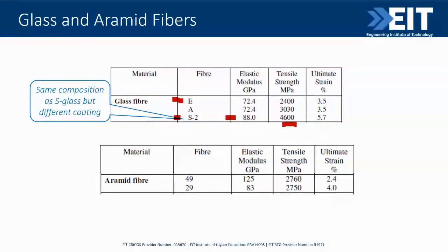That's glass fibers. There's another kind, which is aramid fibers. It's produced by extruding and spinning the solid fiber from a liquid chemical blend. Aramid fibers are quite good in retaining the mechanical properties, up to 400 degrees C, they retain the mechanical properties up to this temperature.